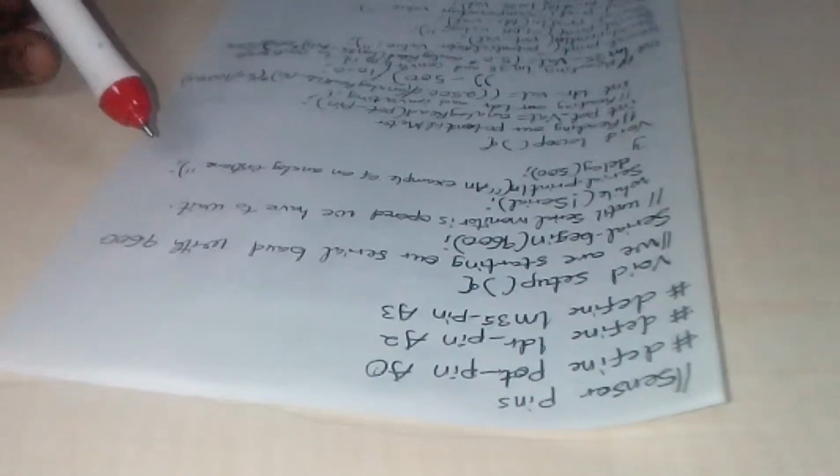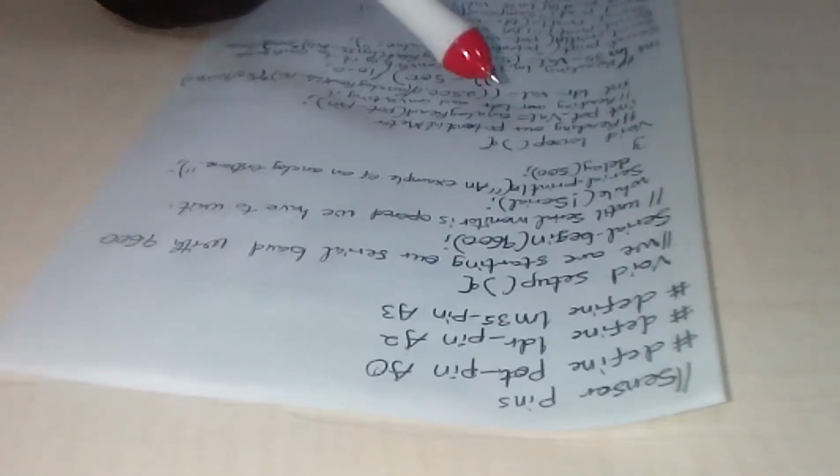It has to really tell us the value. So to be able to tell us the value, we are going to use our serial monitor. There is a serial monitor on our computer when we open our Arduino IDE. We're setting our serial baud rate to 9600. There are different baud rates on our Arduino. So Serial.begin(9600) means it's going to open the 9600 baud.